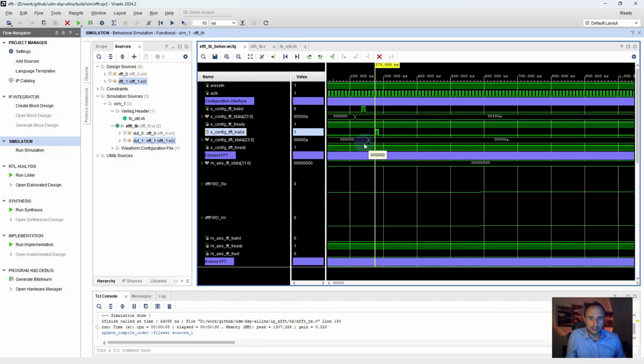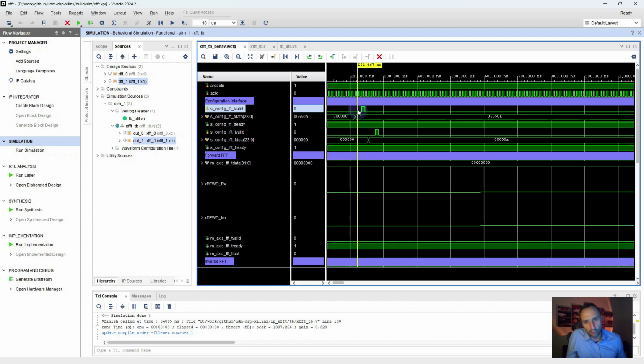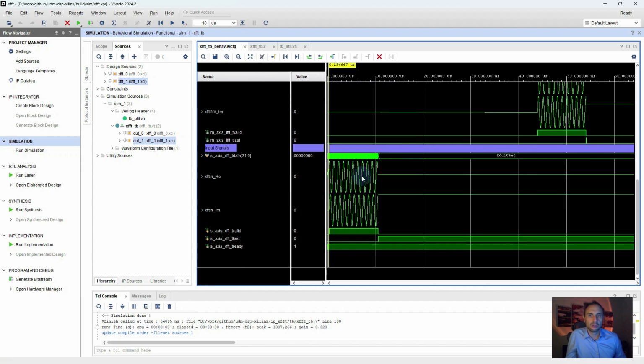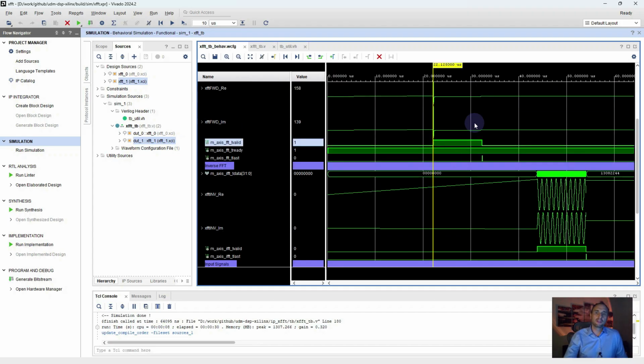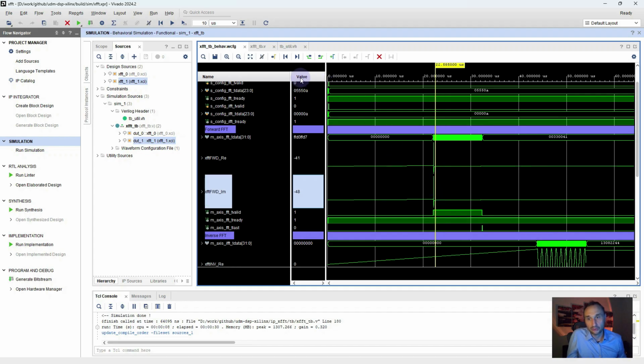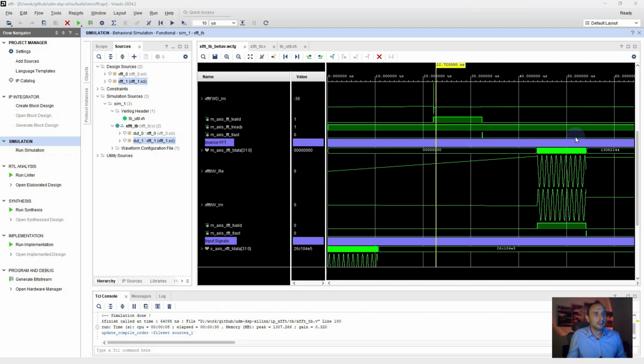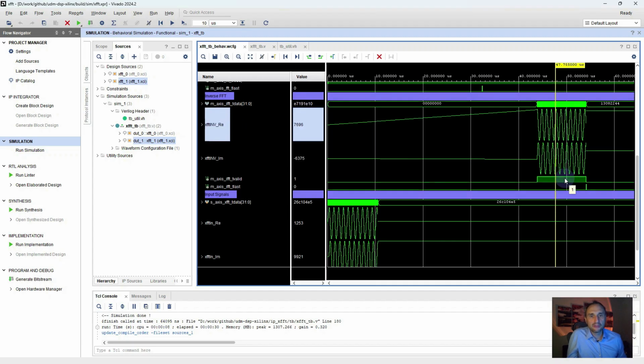So before I provide any input signal, I do the configuration of the IP core. Therefore I am using here the config interface of both instances. In this configuration, I set 1024 points for the transform length. So this is my input signal, and the results after the direct FFT can be seen on both of these plots. Basically, this is a spectrum. This is a spectrum of sinus. It's an expected signal, and this signal I provide as input for the inverse FFT. And this is the output from the inverse FFT configuration.